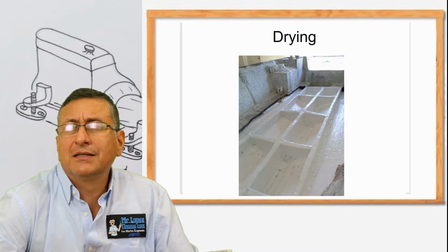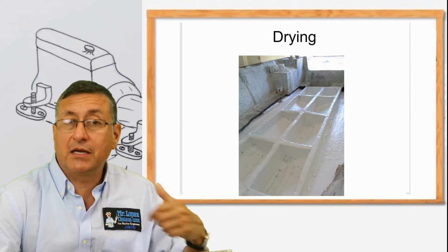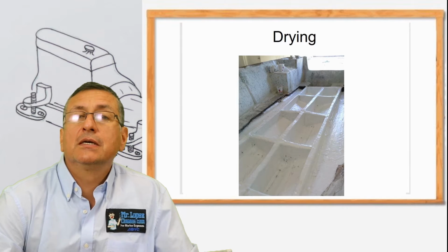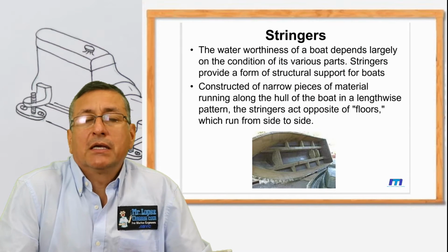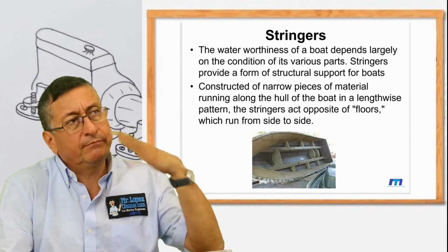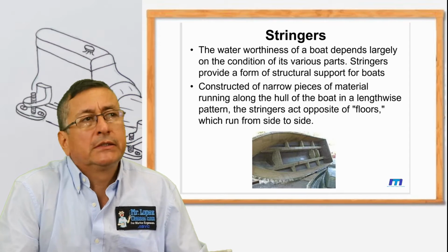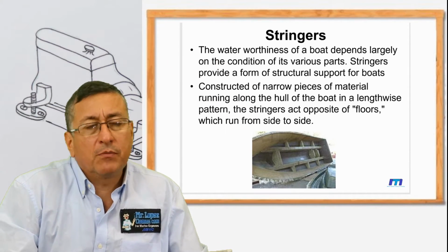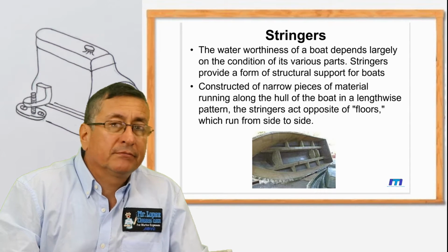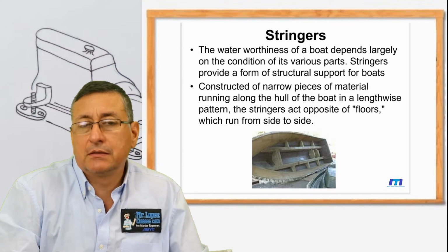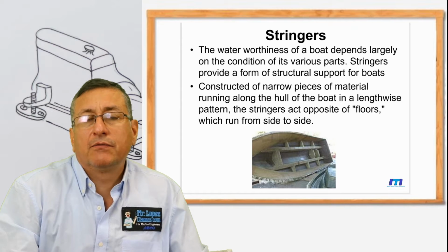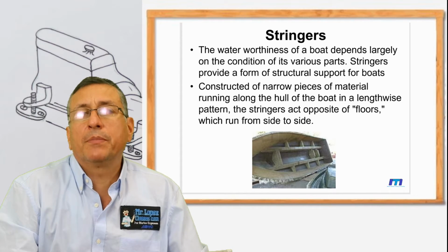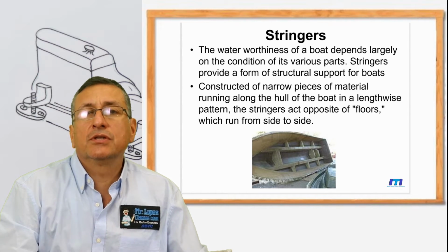Yes, and we did the same with the transom. Right now I am going to show the slides about the transom, but this is a big job. You need to disassemble the boat completely. You need to remove the engines. This is like building the boat again. For that reason, the life of the boat depends on the condition of the stringers and the condition of the transom.